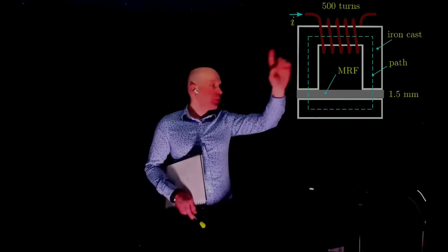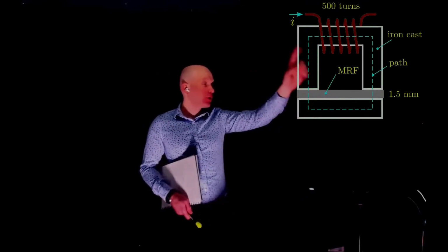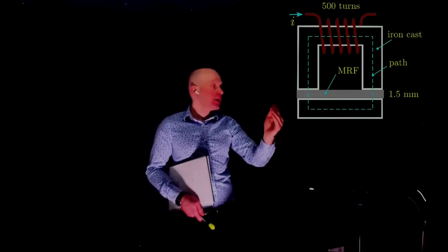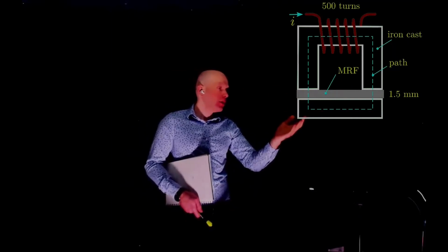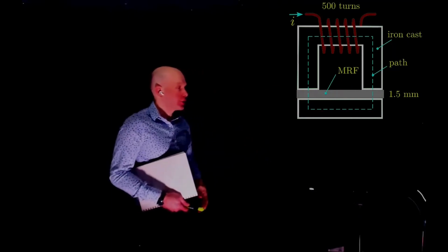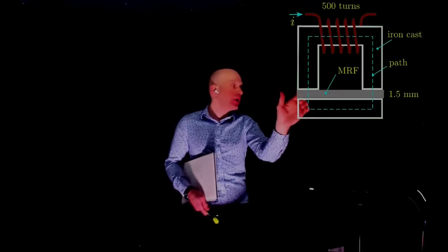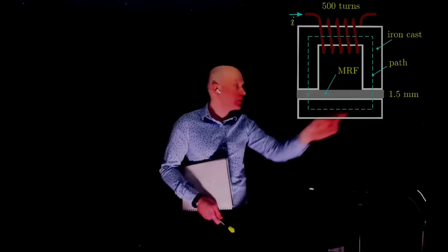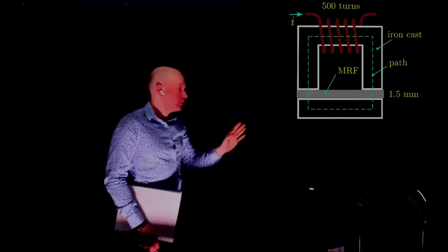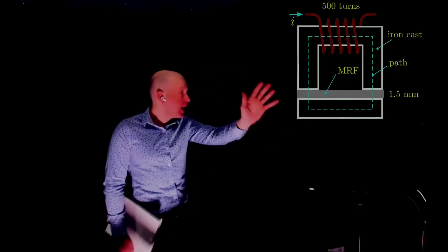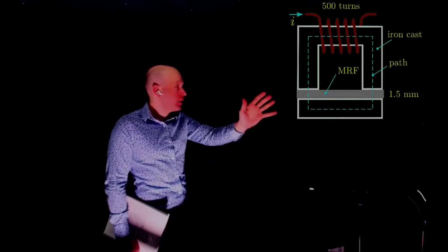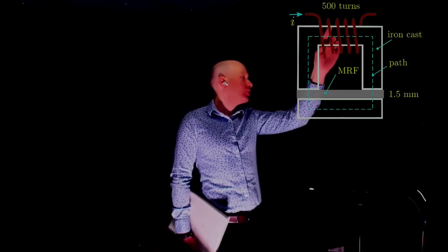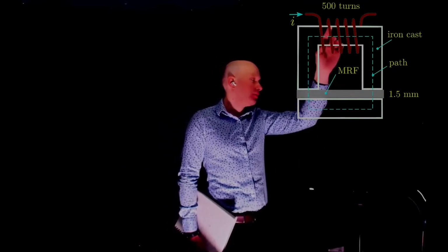We will establish 0.8 Tesla, the same magnetic flux throughout the entire circuit. Because A is constant, then the magnetic flux divided by A, which is B, is also constant throughout the entire circuit. So in order to establish 0.8 Tesla here, we need to establish 0.8 Tesla everywhere in the circuit. Is that clear? Because if this did not have a constant cross-sectional area, establishing 0.8 Tesla here would not necessarily establish 0.8 Tesla there, right?